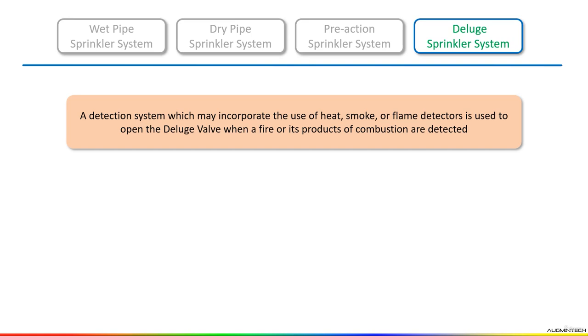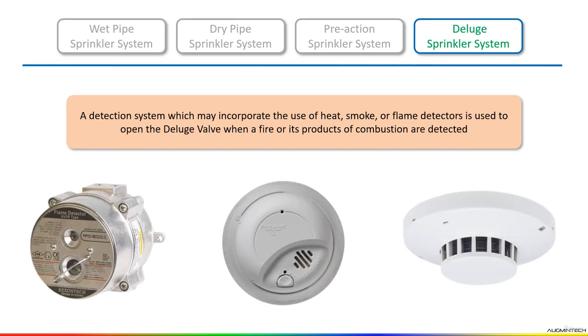So there are many advantages of using deluge system. The major advantages of using deluge fire protection system over other kinds of system are: they can easily control rapidly spreading fire, very quick response as all fire sprinklers are open. Their operation can be made fully automatic. Deluge system being a dry system, no risk of frozen pipes. They can also be used in conjunction with foam concentrate for better controlling certain types of fire.